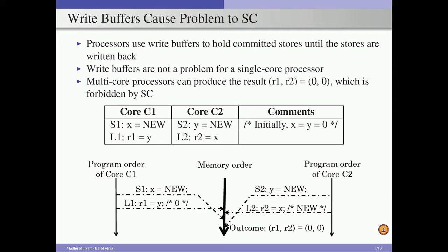But now the question is whether we want to go for sequential consistency or whether we want to utilize the hardware performance optimization techniques. Generally, the processor vendors will go for these hardware based performance optimization techniques, and they want to consider relaxed consistency models, so that the programmer can expect extra outcomes in addition to the sequential consistency model behavior.